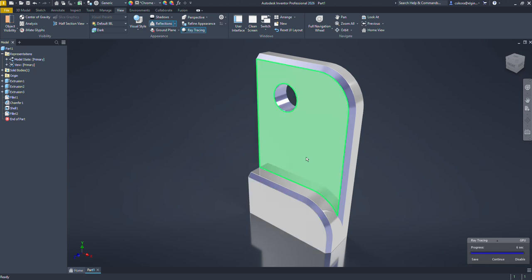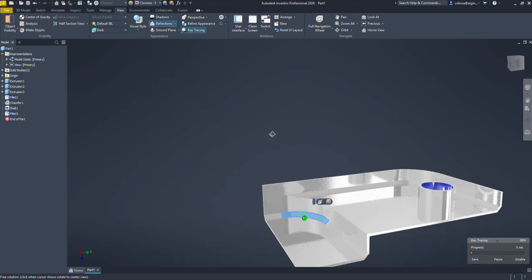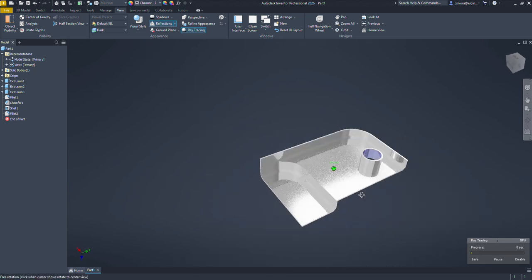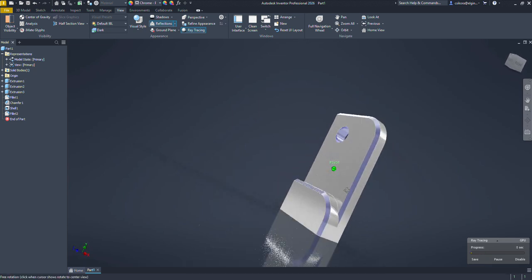We're going to learn how to sketch the profiles first and extrude those out, and then we're going to learn how to put a hole in, as well as how to put fillets, that's a radius like you see right here and here, and then also chamfers, which are angles. That's these blue surfaces here. And if we rotate this around to the back side, we're going to learn how to shell it and create the shell body that you see there. So let's begin.